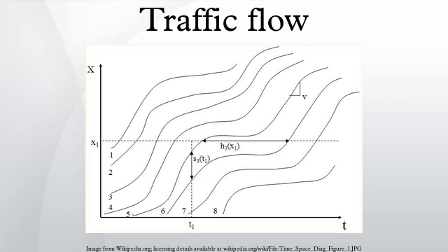Cumulative vehicle count curves. A cumulative vehicle count curve, the N-curve, shows the cumulative number of vehicles that pass a certain location x by time t, measured from the passage of some reference vehicle. This curve can be plotted if the arrival times are known for individual vehicles approaching a location x, and the departure times are also known as they leave location x. Obtaining these arrival and departure times could involve data collection.